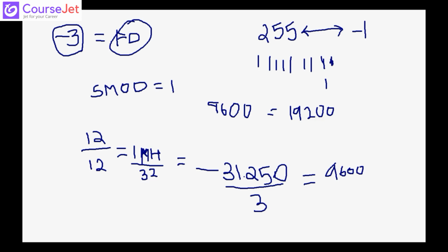Again you are using some SFRs here, which are the SBUF register and SCON register. Then we have seen the TCON register, and we are using a timer here, so we will be using TL, TH, TCON. All these registers are in the SFR, that means from address 80H to FFH in SFR RAM. All these registers are predefined and they are there. You will have a particular address for these bits in SFR RAM. Now we will write one program for transmitting and receiving your data.